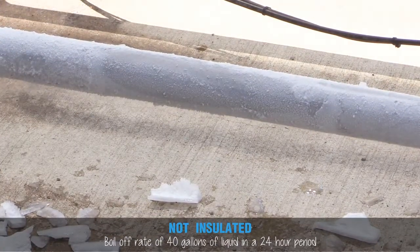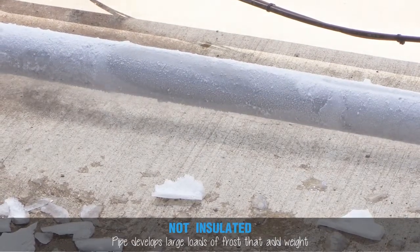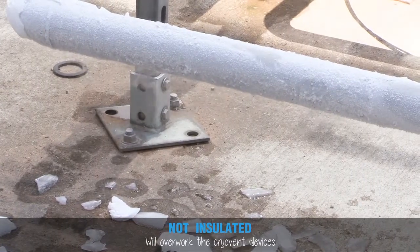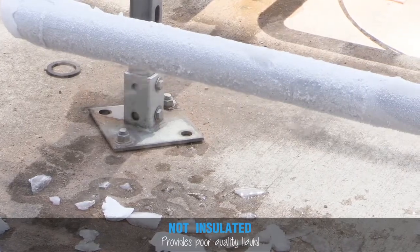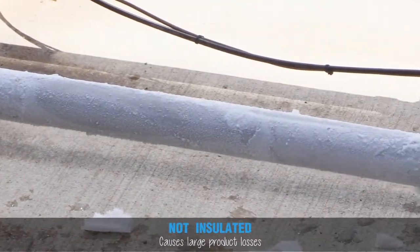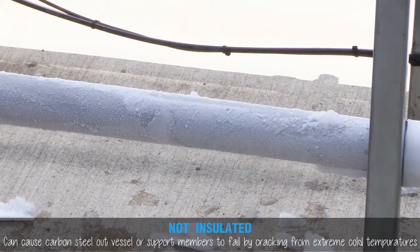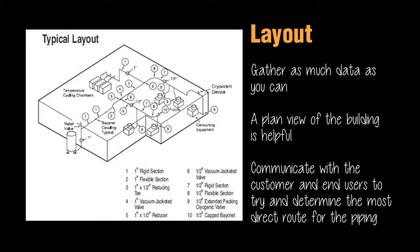These non-insulated sections also will develop large loads of frost that can add weight to the pipe and cause failure. They can encapsulate valves and reliefs, rendering them inoperable. It will overwork cryo vent devices in the system. It can and will cause tank pressure problems. It does provide very poor quality liquid for our processes, and it also causes large product losses. And in the worst case, it can cause carbon steel outer vessel or support members to fail by cracking due to extremely cold temperatures.